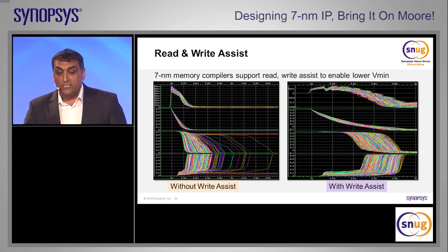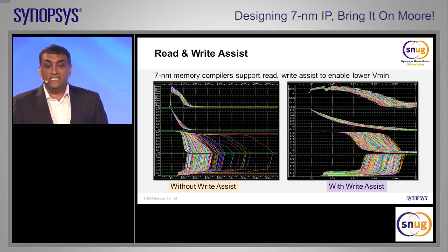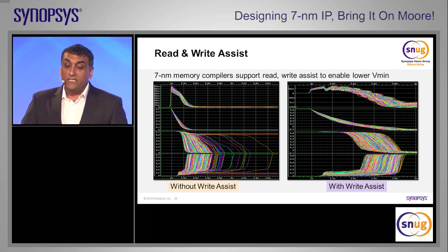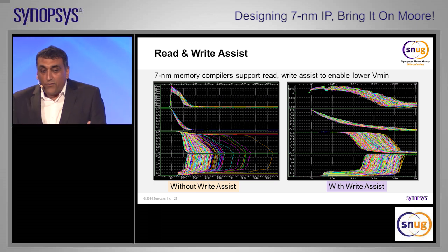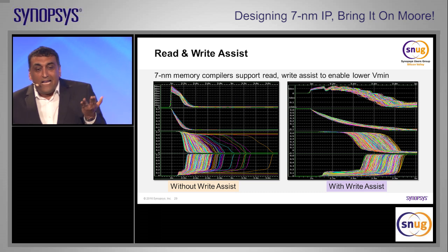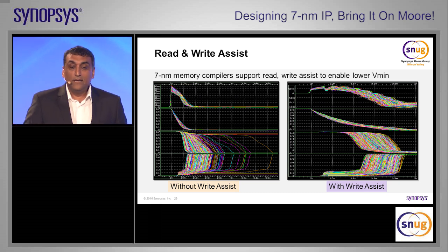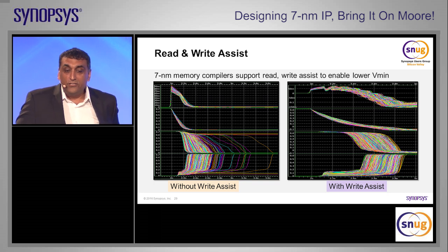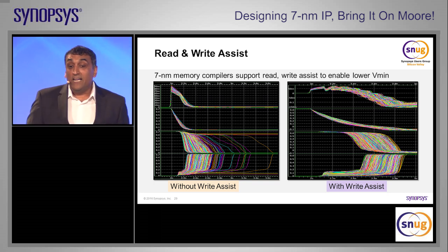In this particular example, you won't be able to read the text, but I can read it from here. You're basically looking at about 230 fails in 10,000 Monte Carlo runs with a 0.63 volt supply. When you up it a little bit to 0.7 of a volt, you get a handful of failures when you do it over 10,000 times running Monte Carlo. The point is that the DC write margin shows one fail at about 720 millivolts in 100,000 runs.